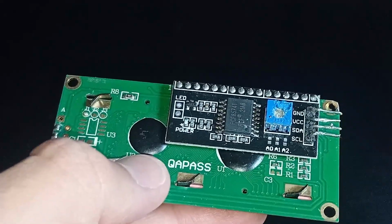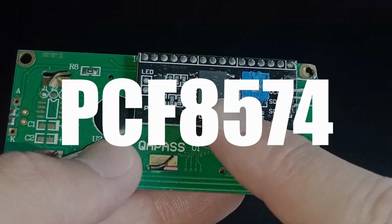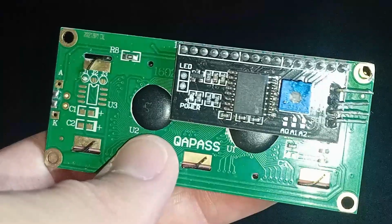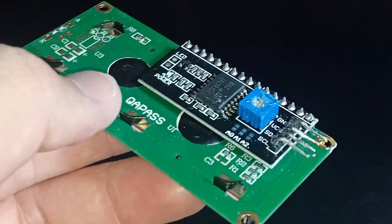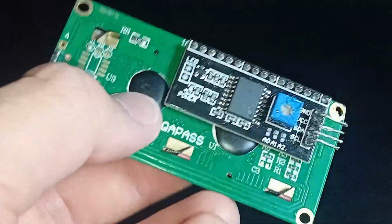This adapter typically contains a chip called PCF8574. This integrated circuit acts as an I2C input-output expander. In simple terms, it's what adds I2C communication to the LCD. And by the way, this chip isn't limited to LCDs. It can also be used with LEDs, sensors, and other modules.